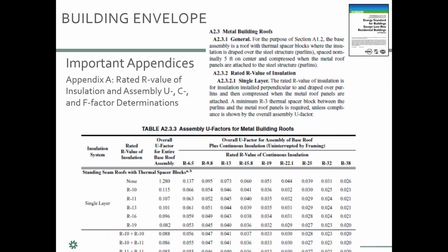We're playing in the big leagues here, and issues like thermal bridging are really critical. You might put R13 in the cavity with a steel stud, but the reality is that an R13 in a 2x4, 16-inch on center cavity, the effective R value is not 13. It's actually less than half of that. It's only 6.